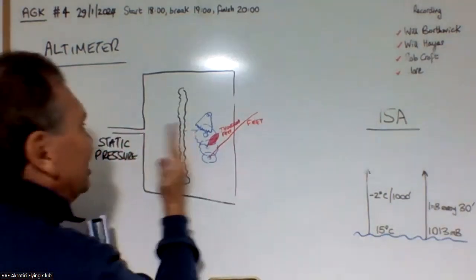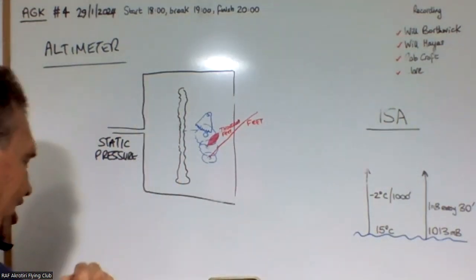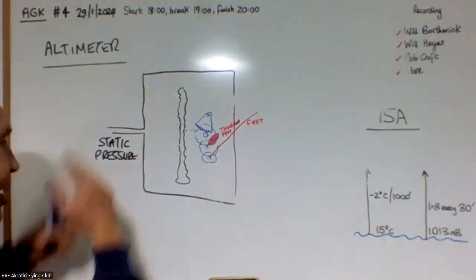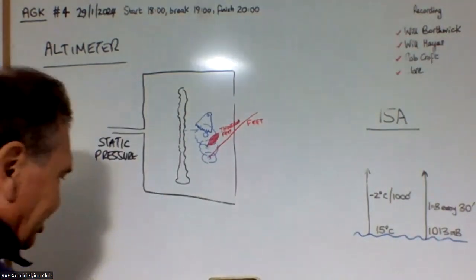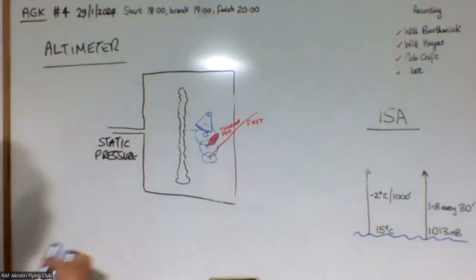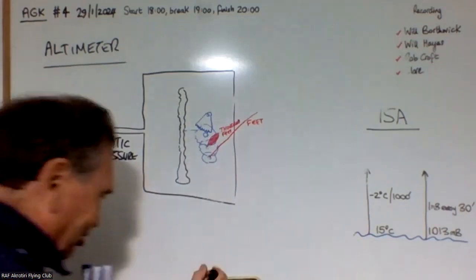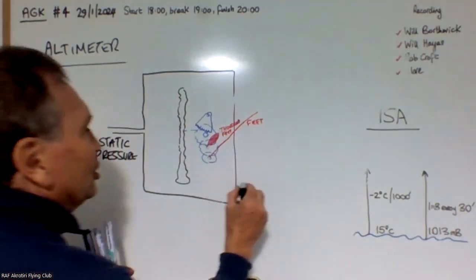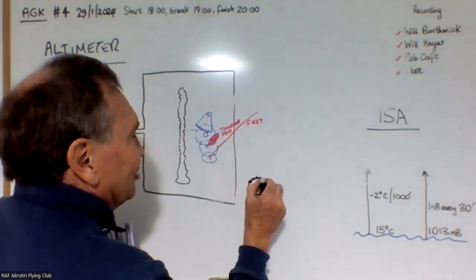So all this is really doing is just showing you the pressure. But of course it's calibrated to convert that pressure into an altitude. And a precision altimeter actually has this subscale on it, where you can adjust an extra knob on the front of it.